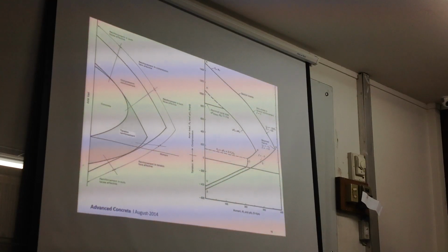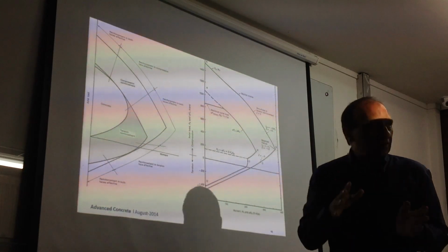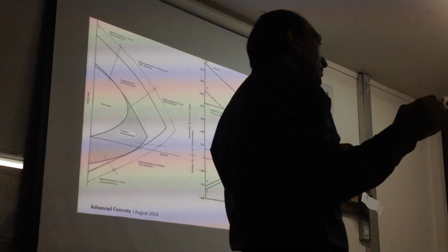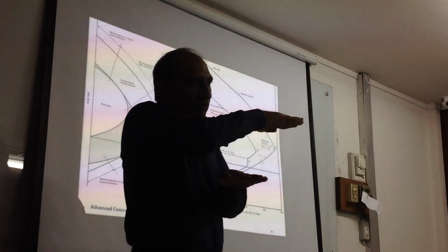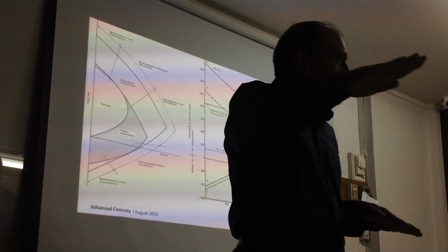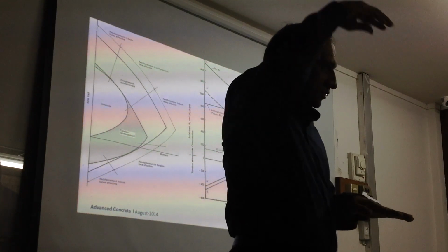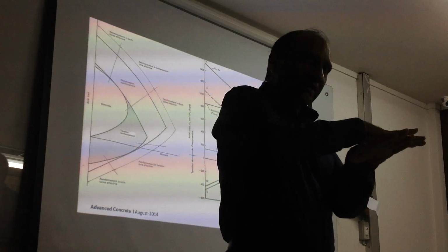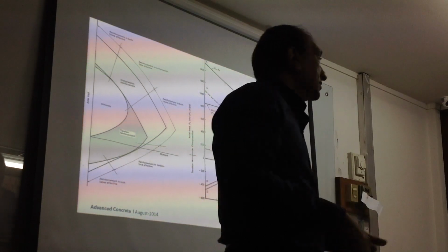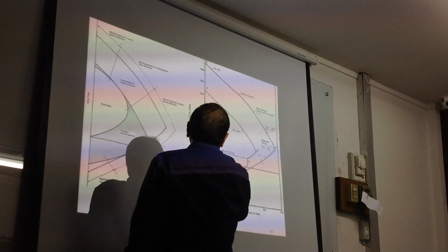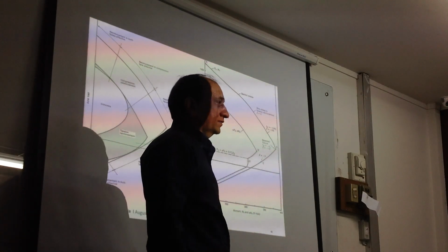That produces a special case of pure compression, all compression on the section only. Then there is a special case where the neutral axis is at infinity, all the section under uniform stress. Just axial load, no moment. So the entire section will have uniform strain, uniform stress. That is called the P0 case, the zero moment case. This calculates that point on the curve.